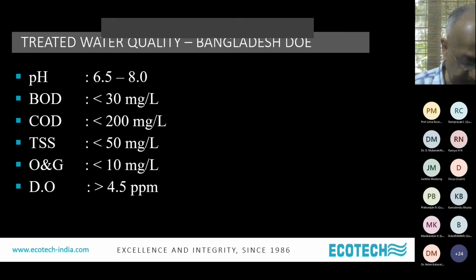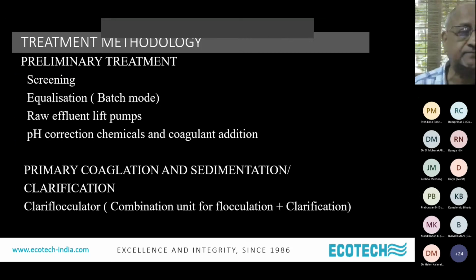Introduce a dissolved oxygen requirement in treated domestic wastewater or industrial wastewater, because most of the wastewaters finally end up in lakes and rivers, where the flora and fauna can get affected if the dissolved oxygen, typically from a treatment plant, industrial wastewater or a domestic sewage treatment plant, will be in the region of only 2, 2.5 or 3 max by the time it reaches the water bodies.